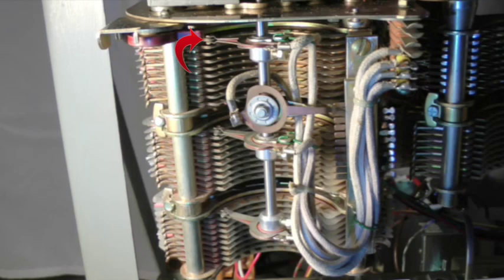If neither of the upper or lower sleeve terminals on which the sleeve wipers are resting has negative 48-volt battery from the CO relay winding in the line circuit, then these terminals are not the bank terminals of the line requesting service. In this case, more rotary stepping is necessary. In our example, the line requesting service is on the 10th rotary position, and so there is no battery present on terminals 1 through 9. The rotary stepping cycle will be repeated for rotary positions 2 through 9. Let's look at the rotary position 2 stepping cycle.